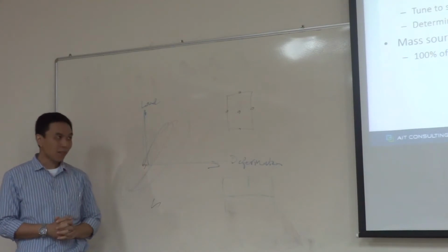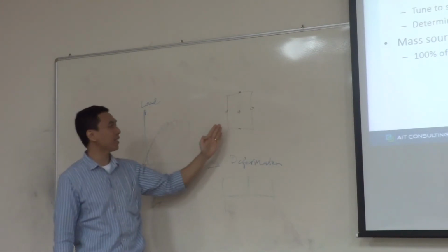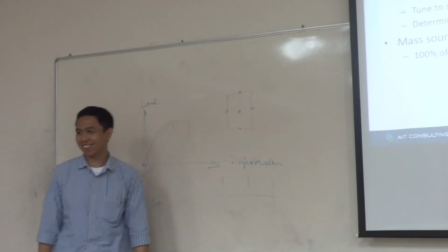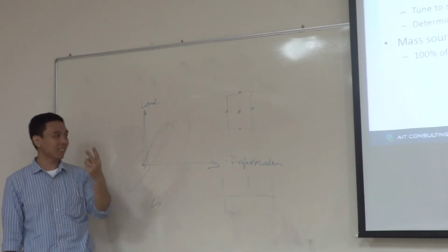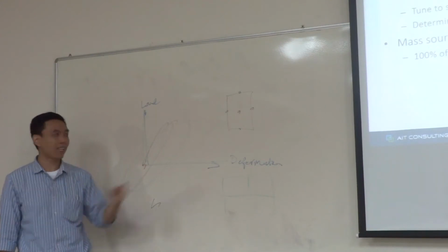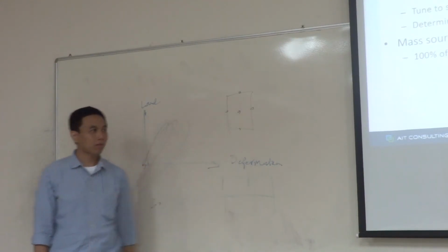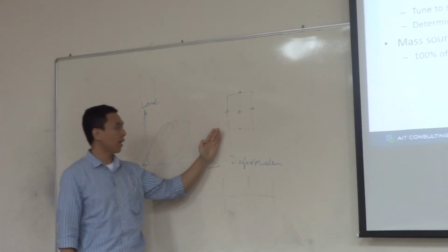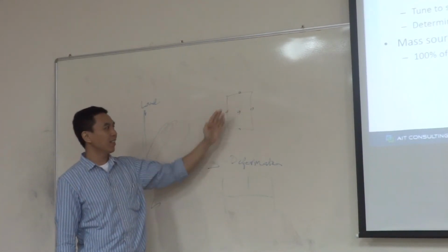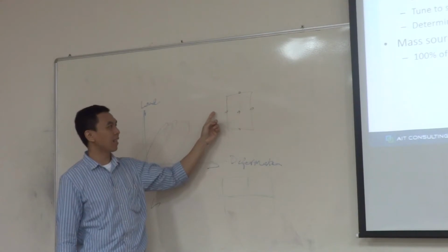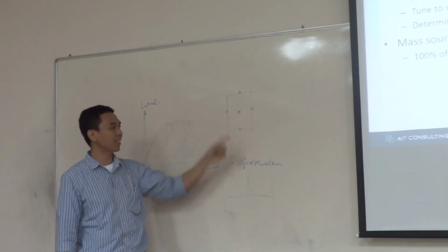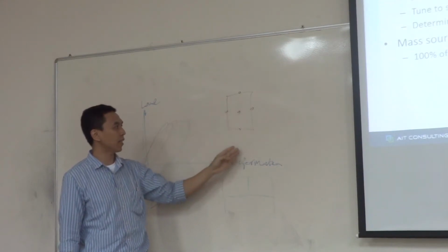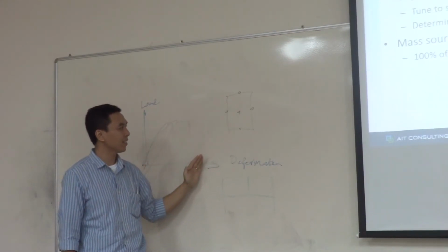But we cannot design the building by applying the earthquake at every 360 degrees. In many cases, we just design in two directions only, X and Y. So in case the earthquake comes from a diagonal direction, we are not sure whether the member capacity designed from the X and Y directions is adequate or not.